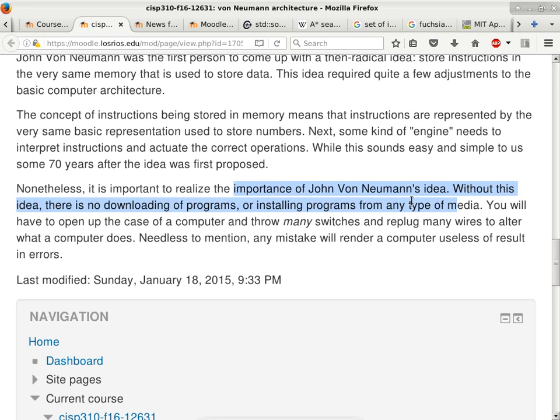So I have to write the firmware, and the firmware exists only in EEPROMs. So if I make a mistake, it doesn't work, I have to remove the chip from the board, okay, but they're in sockets, which makes it a lot easier, okay? So you just use a socket, you get it out of the board, you get the next one in, because it doesn't make any sense to only use one single EEPROM chip. So I usually have like 10 of these things, so I can basically just use up all 10, then I erase 10 all at the same time, then I have 10 available to do the debugging. But there's no tool to do the debugging other than a single LED in most cases.